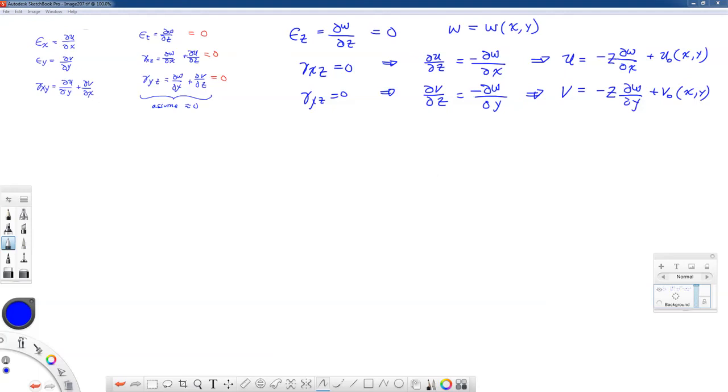In the stress normal to the midplane, sigma z is small compared with the other components of stress and can be neglected. All right, so we are restricting ourselves a little bit. And the u naught and v naught represent offsets of the midplane. As far as our concerns right now, we're going to neglect those. Later on, if I get a chance to talk about composite materials or some different situations, we can incorporate those terms again. But for now, we're going to neglect u naught and v naught.